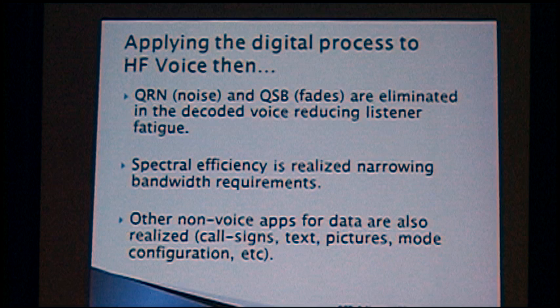So applying this digital process to HF, we've effectively gotten rid of noise. And another problem that we have with analog, of course, is the QSB fades. They're eliminated. So we reduce listener fatigue. And Kurt talked a little bit earlier, some of you may have been over there, with the FCC about realizing the benefits through narrowing the RF spectrum. We found that we can do this and have pretty good voice quality in half of what we have with sideband today.